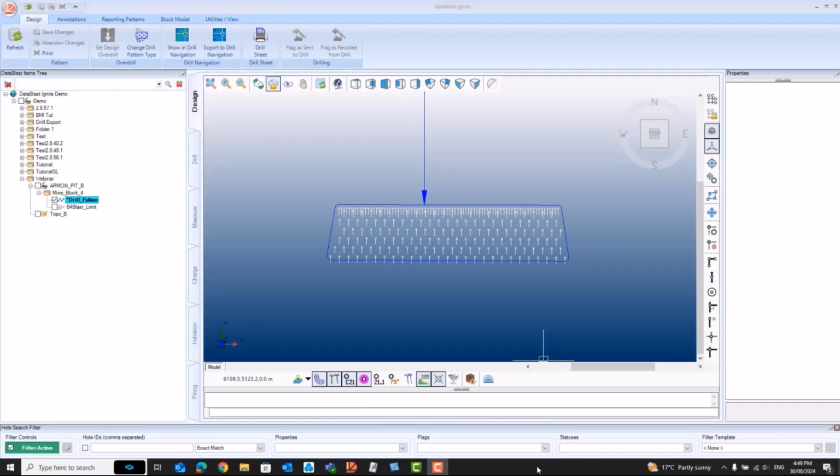The drill pattern in front of you is an 89mm 4x4 meter staggered bench blast with a design angle of 15 degrees and a 10.35 meter depth. The pre-split holes are 89mm holes spaced 1.5 meters apart with an angle of 15 degrees and a depth of approximately 10 meters. I'll be using this pattern to demonstrate our new Drill and Blast software version 2.9 beta.